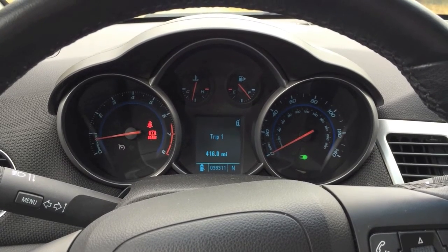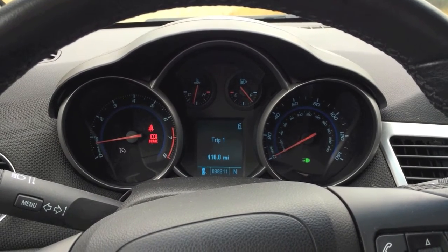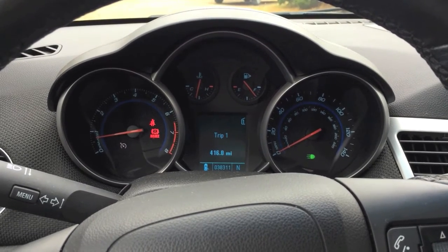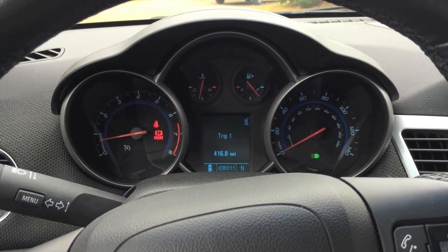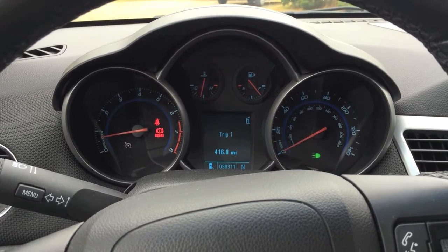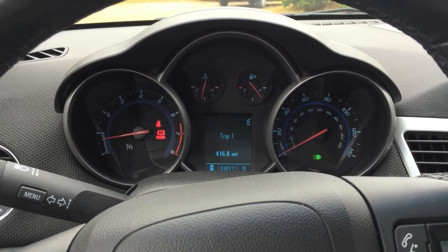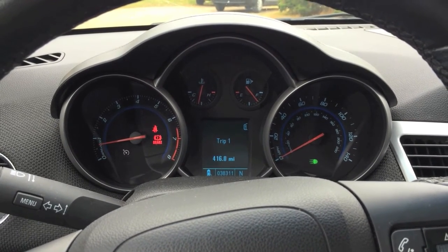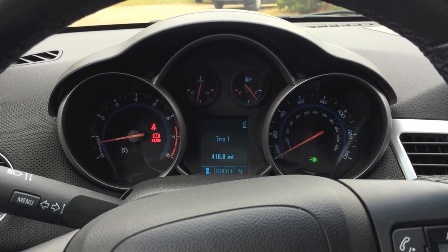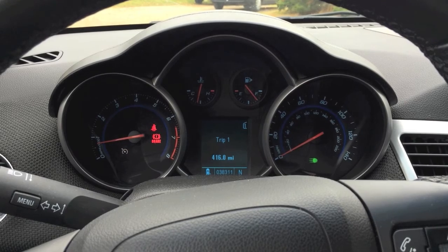Alright guys, inside the car right now, got the battery hooked back up. We actually took it for a long ride. One of the things I like to do before hooking up the computer to the car and resetting the check engine light, I like having that battery disconnected for a couple minutes and then connecting it and taking it for a long drive. This will give the engine computer time to communicate with the engine and see if it can fix it itself without hooking up the computer to it. And in this case, that's exactly what it did. So as we were driving, the computer sensed that the connection point was back on and the check engine light went off. We didn't even have to do anything else.